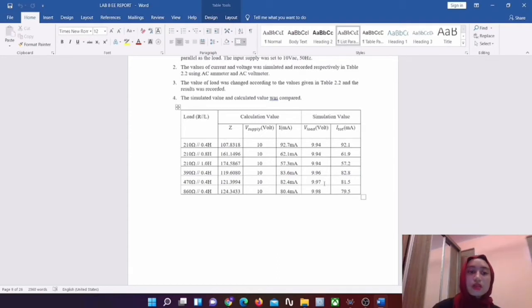So it's because of the use of a small resistor to put some impedance in the loop, which is probably realistic anyway, without changing the operation of the circuit too much, and the value also didn't change too much. The difference can also be because of rounding off the values in the manual calculation, and adding a resistor in the simulation software makes it a little bit different, but the difference is only a small value and almost near to each other.